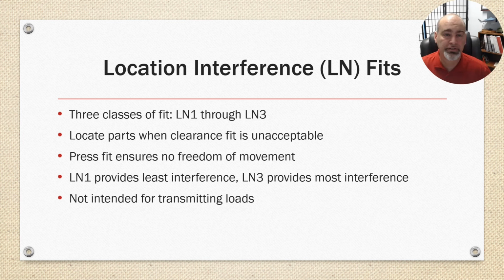It is an interference fit, so once you put them together, you've got to press them apart or drill something out, but they're not intended for transmitting load. They're just for locating parts.